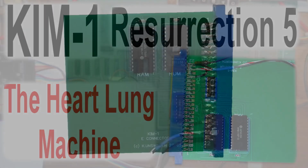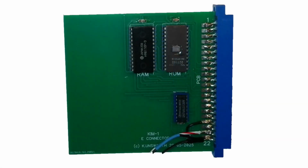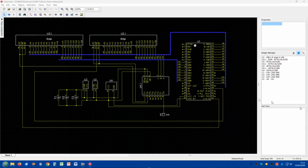In this episode we'll be looking at this board, which we're going to be using to test the D0 and D6 lines to see where the problem lies. I created this small board. This is the edge connector that's going to plug into the KIM-1. And over here there's a ROM chip on it, a 2K ROM and 2K of RAM. It is an extension to the address decoding.